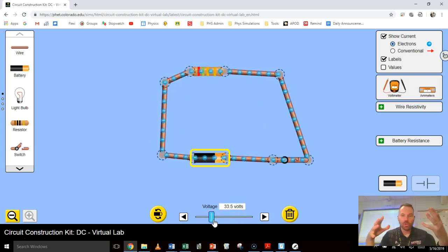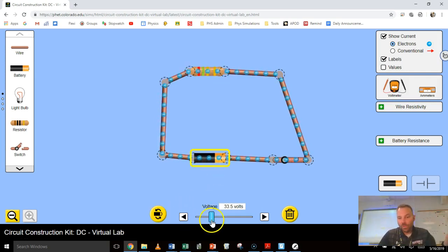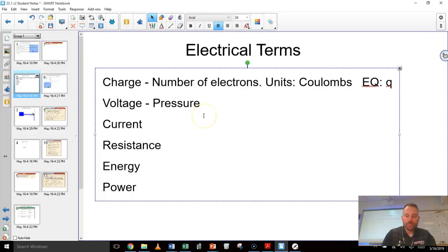So this is why in your walls, you have to have, depending upon how much resistance is there, what device you're plugging in, too much current can flow and then start your house on fire. So you have to have certain wires rated for certain amounts of current. So the more pressure you have, the more electricity flows. Pressure. The units are pretty clever. They're volts. And in an equation, you're going to see the voltage with the letter V.